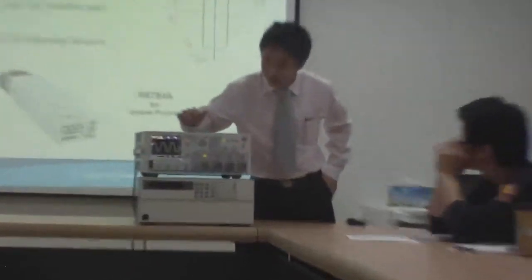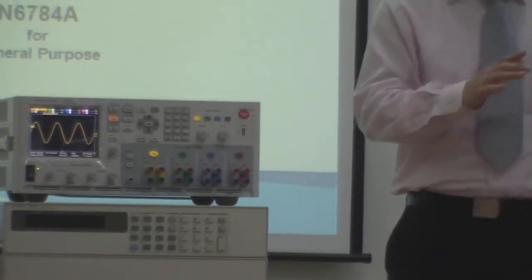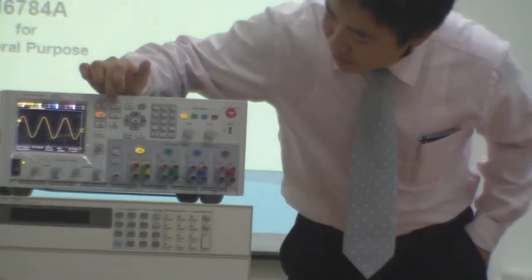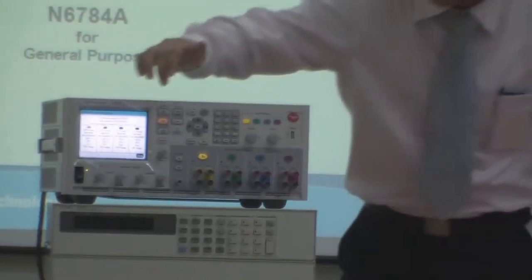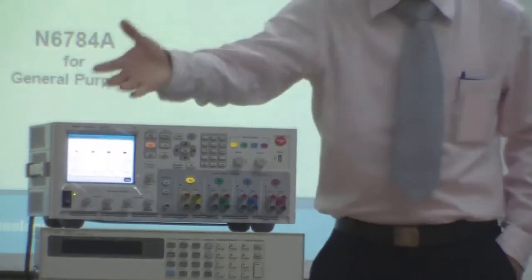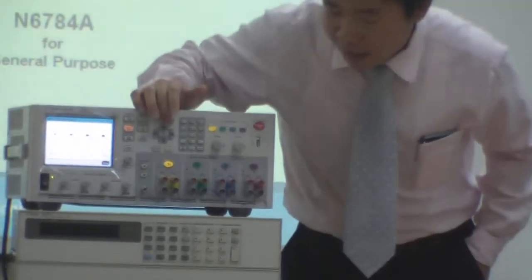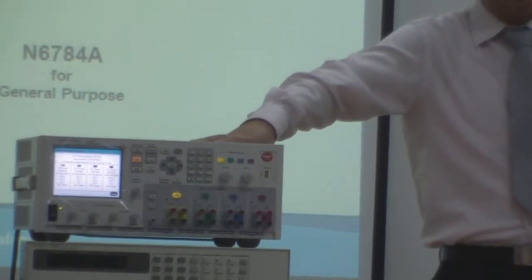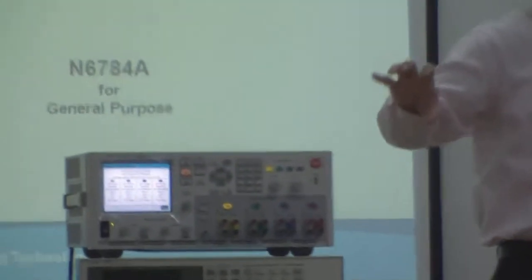Minimum amplitude. So it depends on the modules. Typically, most people ask what the maximum amplitude is, and that is based on the rating of the module. So I'll explain: for maximum amplitude, you look at the voltage rating, and that gives you your maximum amplitude. For minimum amplitude, you can program it to very low levels. I've done it in millivolts, like 10 or 20 millivolts. You can do that for this module.